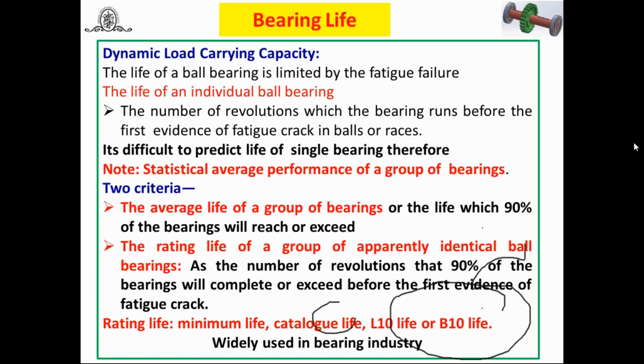It's okay. Then another important, some of the terms associated with rolling contact bearings are bearing life. How to find out the bearing life? That is very important because while selecting the bearing in your industrial gearbox design also, you have to assume how much time you are going to run this industrial gearbox, whether 8 hours, 16 hours, 24 hours. And based on that, you have to assume the bearing life. And based on that, you are going to select the bearing for your particular application.